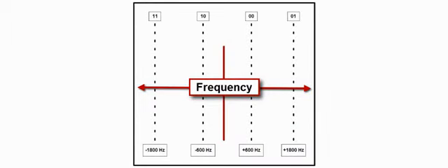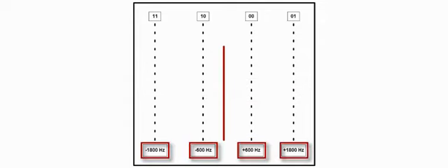Consider this spectrum analyzer display. The horizontal axis represents frequency. The unmodulated carrier is in the center frequency of its channel. This chart represents the 4 states of the C4FM modulation. Likewise, the horizontal axis represents frequency. The red vertical line indicates the center frequency of the channel. Each of the vertical black lines represents a frequency offset from the center frequency of the channel. The frequency offsets are minus 1800 Hz, minus 600 Hz, plus 600 Hz, and plus 1800 Hz.